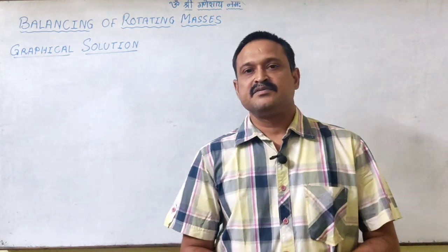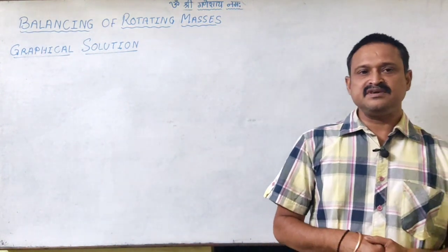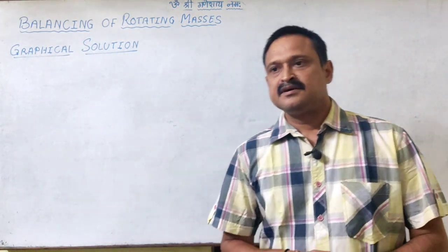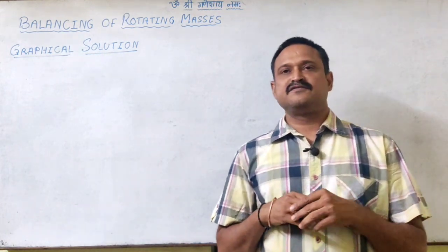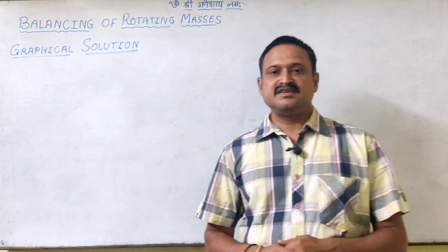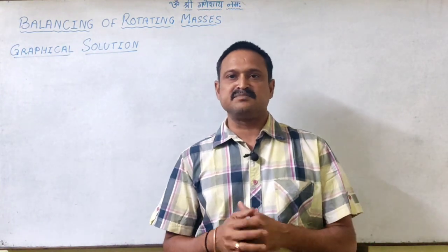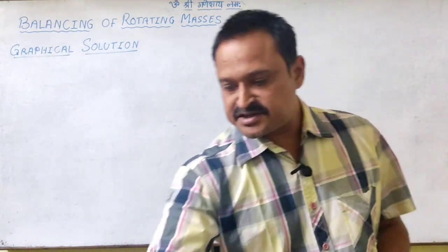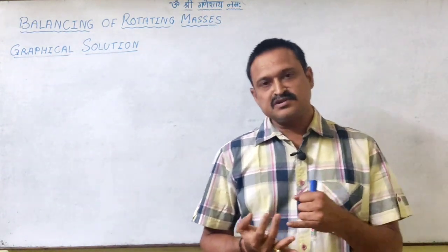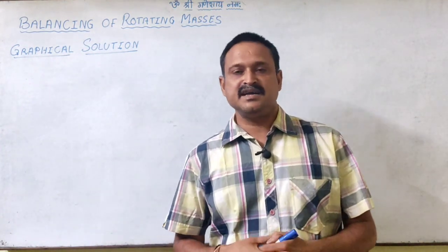In the last session, we have seen how unbalance is getting into the system, and we have as well understood how we can balance this system with the help of introduction of an external mass in the system to balance those inertia forces which are creating trouble, and we can make the system run smoothly. Out of which we have seen there are unbalances due to the pure rotating masses, due to the reciprocating masses, and the masses which are having combined motion.